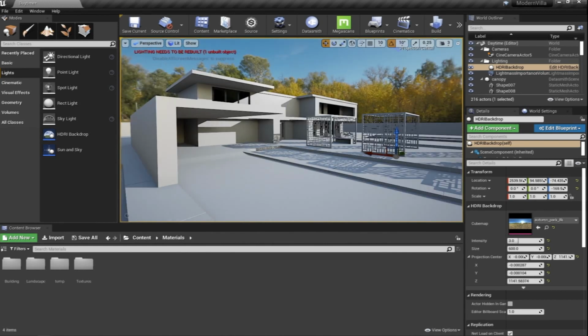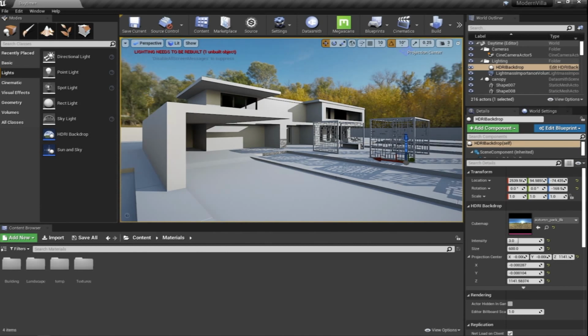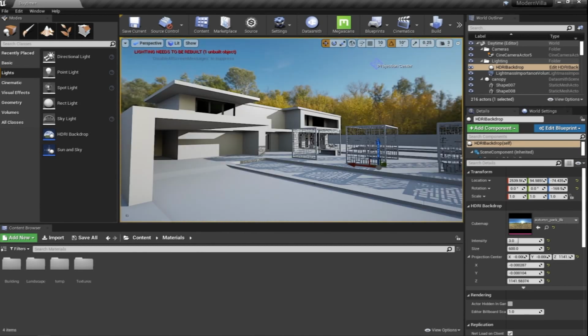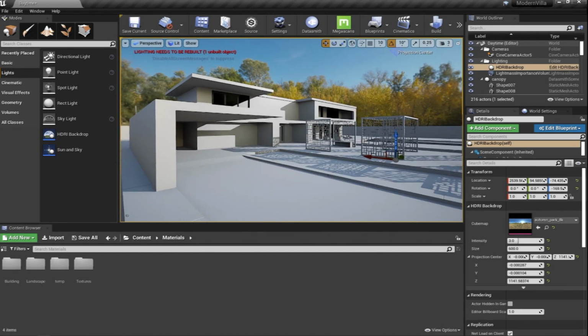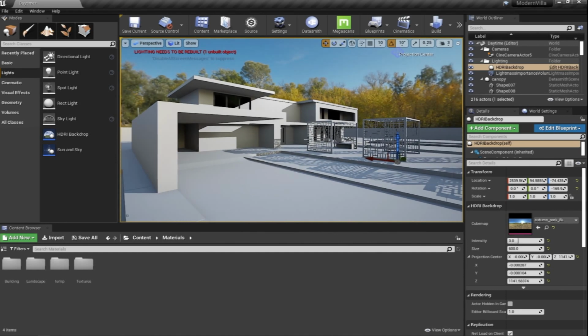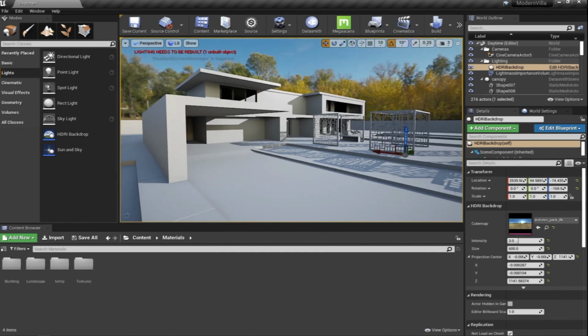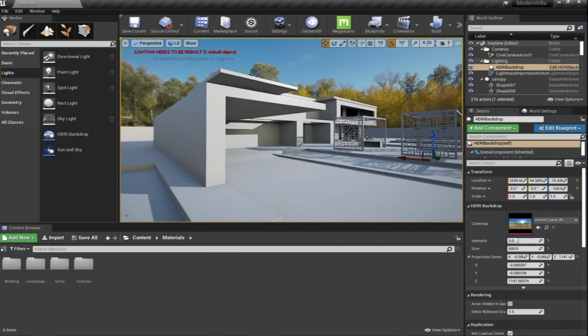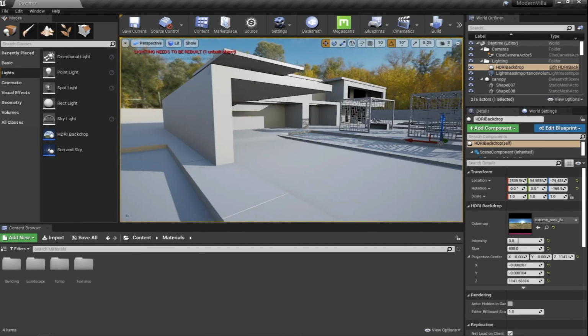And as you know, the key to your architectural realism is how you can create your materials to react realistically to the light setup that you have used, in terms of the diffuse channel or the normal channels, that is the bump channel if we are talking about 3D Max, for example, and also for the roughness and the reflection. All of these values, if you can manage to set them up right, you can actually get a realistic look of your material. So let's get started.